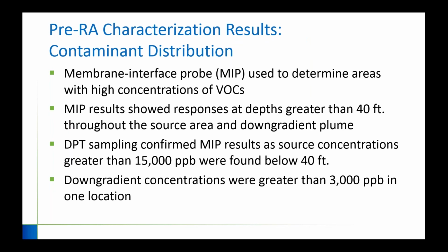What we saw, as you might expect, is concentrations something like 10 times higher than what was ever observed historically at the site, just because we're getting that greater resolution. We're going and sampling specific zones. So as was said before, we didn't try to correlate a MIP response to a specific solvent concentration. We used the MIP to identify zones we needed to go sample, and then we went in with the DPT